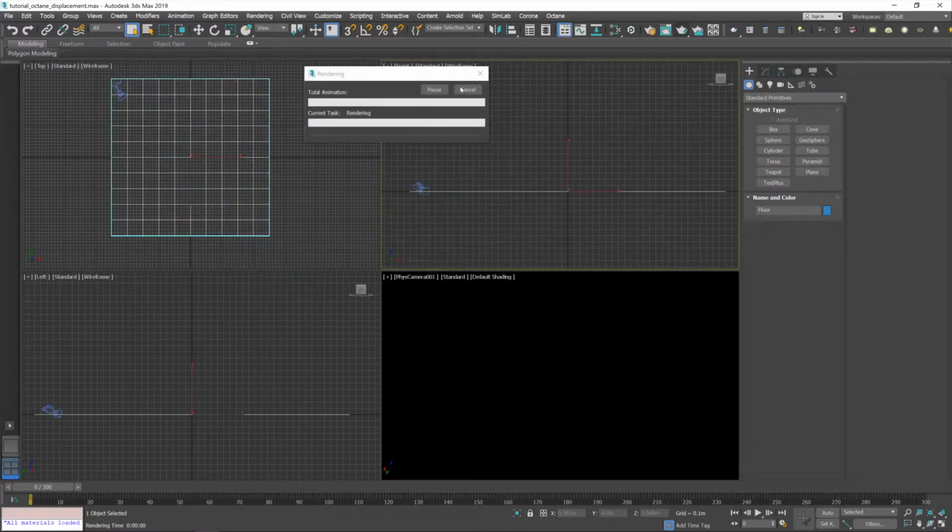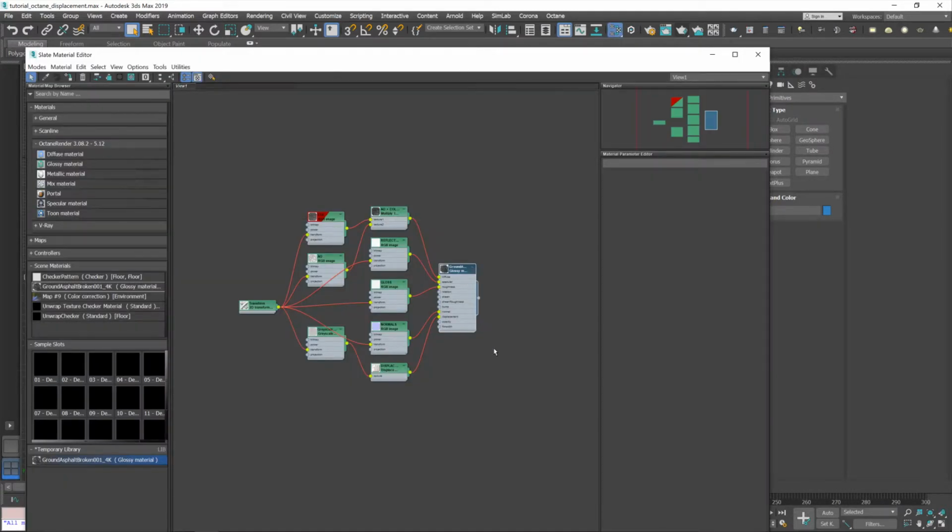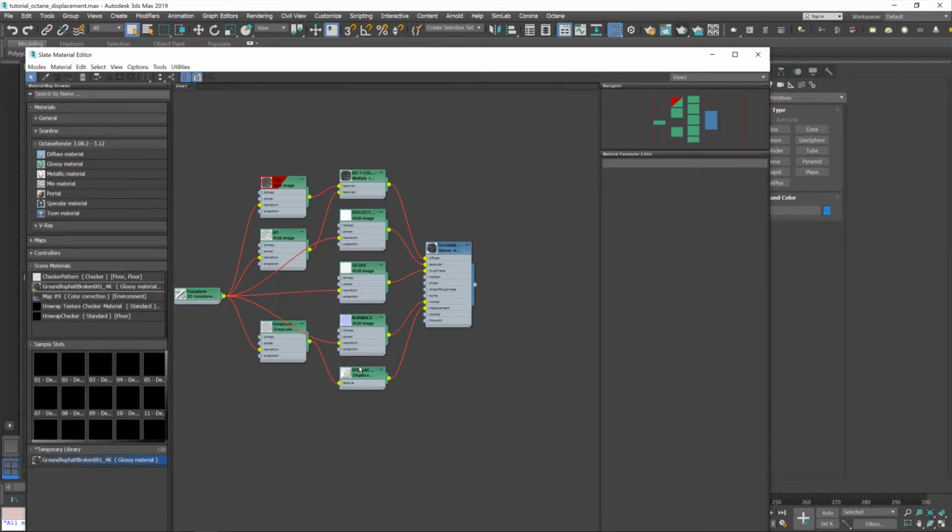What you'll need to do, though, when you're bringing in materials is just make minor adjustments depending on the material itself. So to do that, you'll go to the material, then down to this displacement node here, and the settings for the displacement are here. So we don't have that much we need to adjust. You've got the height, which will dictate the overall amount of displacement. High numbers for more, low numbers for less. And this level of detail, which I'm going to set to 4096, as that's the resolution of the texture that I've downloaded.